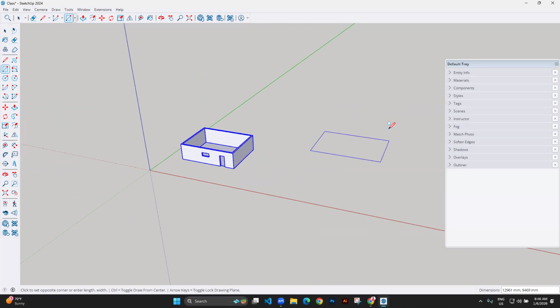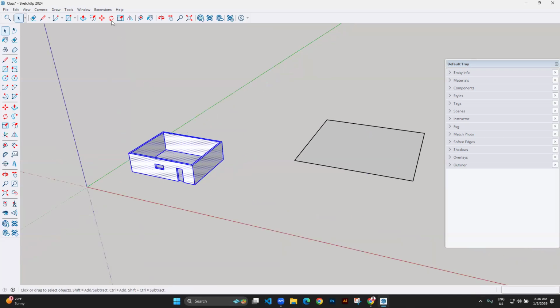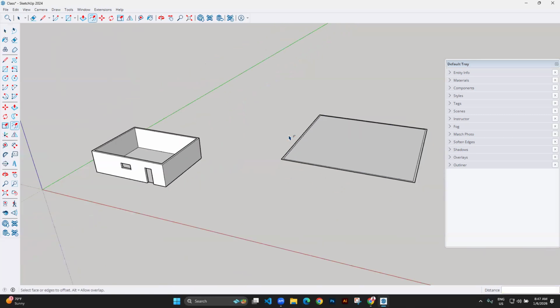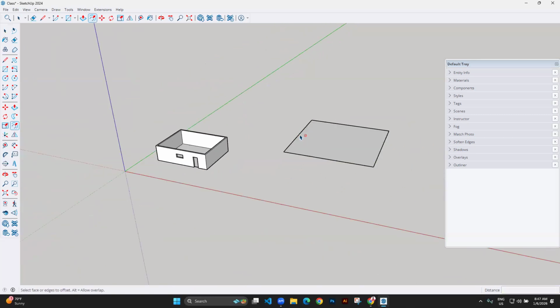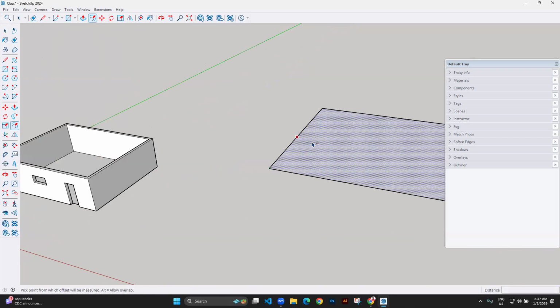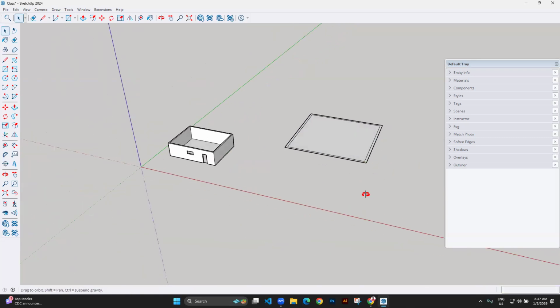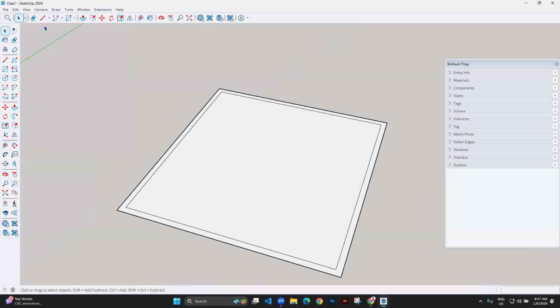The better way of doing it can still be almost the same, but the approach is different. I'm going to offset this. After offsetting with 230, now I want my walls to be separate, so let me do 460. I want to be push-pulling these walls individually, like four of them. So how do I do that?